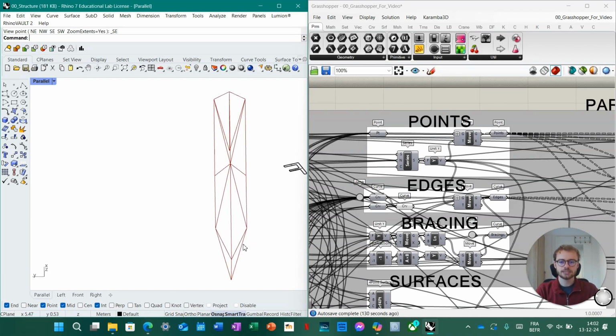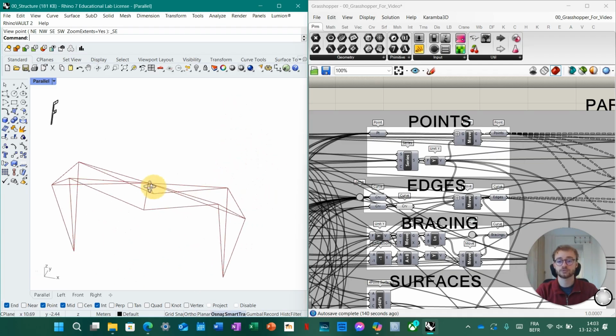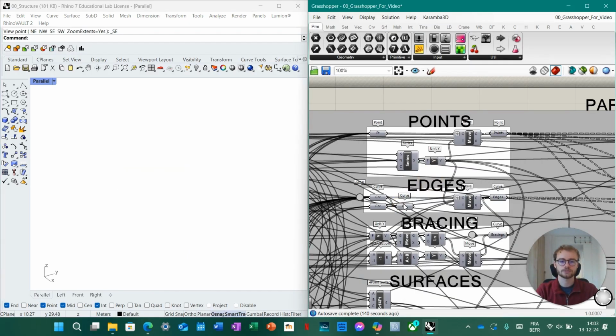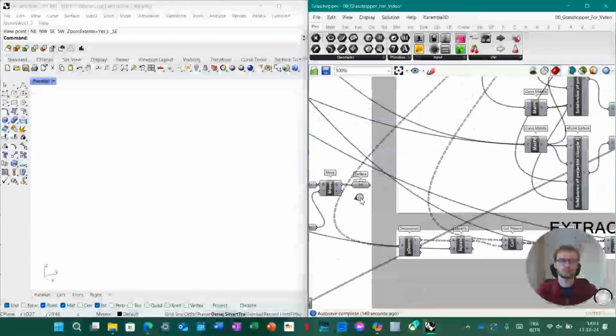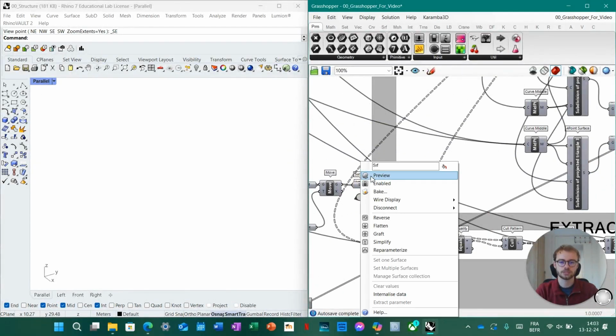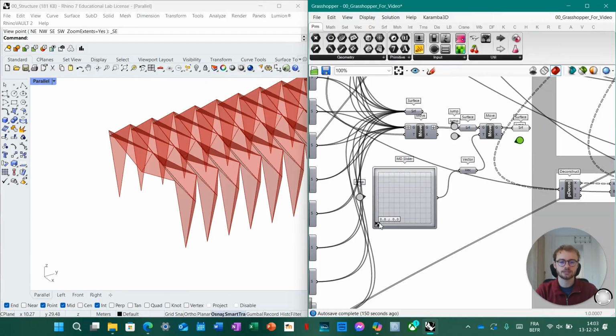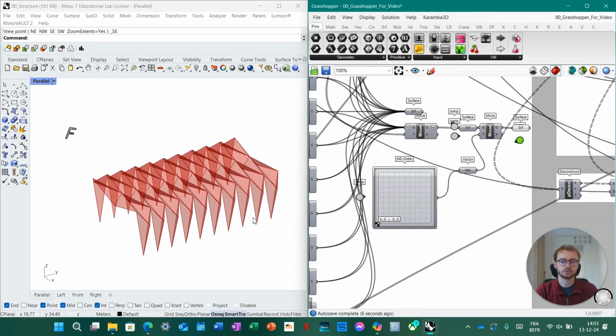So what you can see is that you have triangles everywhere. So your structure really needs to be fully triangulated in order to work, and this is really crucial. But obviously that's not all, and that's not sufficient by itself. Something else that you may want to be careful about is ensuring that your structure cannot slide. See, for example, here I could move my structure around, and that's not my goal.